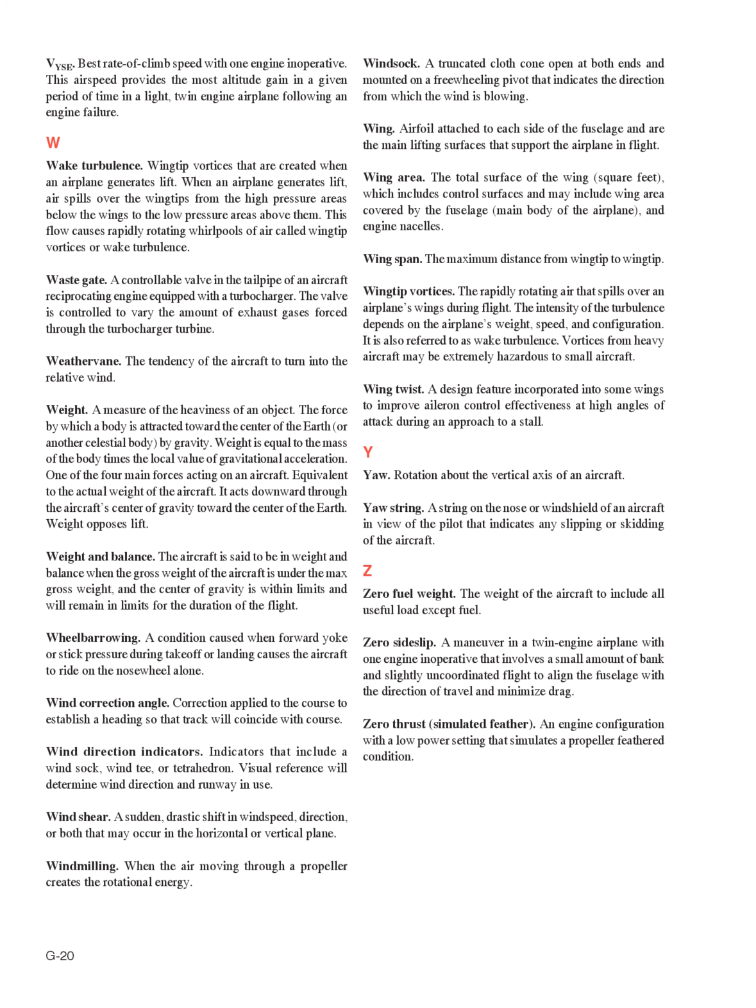Wake turbulence. Wingtip vortices that are created when an airplane generates lift. When an airplane generates lift, air spills over the wingtips from the high-pressure areas below the wings to the low-pressure areas above them. This flow causes rapidly rotating whirlpools of air called wingtip vortices or wake turbulence.